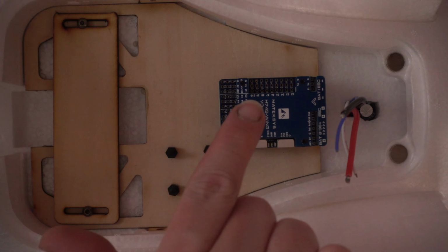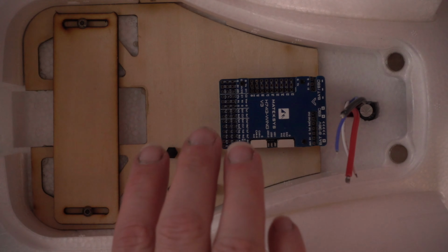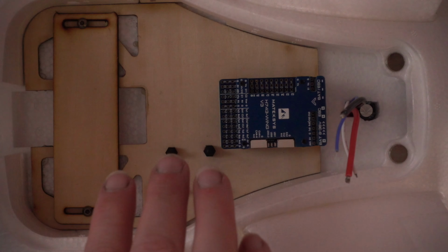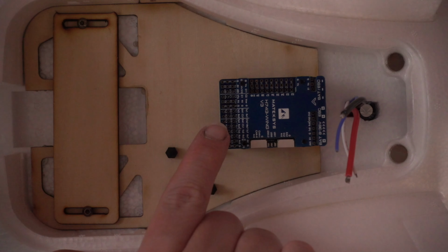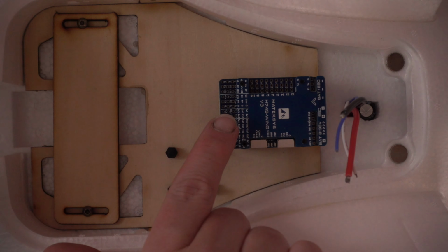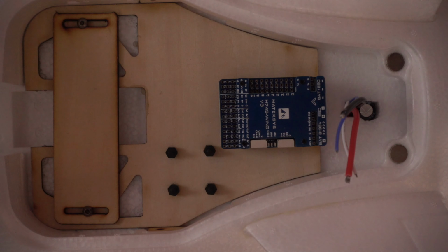So for the initial setup, the receiver and VTX will be in this bay, but we'll be moving out onto the wings later on. Also in a later video, I'll be adding smart audio, so that will be connecting to one of these UARTs here. And I'll also add a second camera, just so that there's a few bases covered for if you want to do that kind of thing, but I can do those bits in separate videos after the initial build.